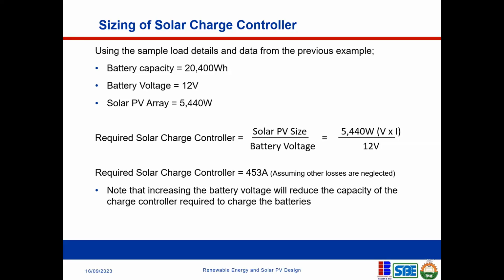If these systems are not in place, maybe you don't have a charge controller to monitor the charge of your battery, or you don't have a battery management system that controls the charge and discharge of your battery, your battery can explode. It can kill the cells, it can damage the cells of the battery and create a whole lot of problems. So it's not advisable. All right, thank you.